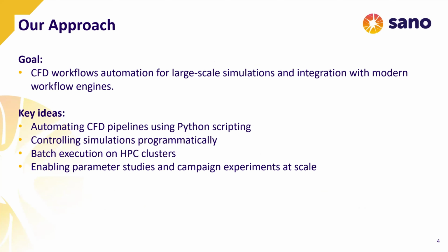From the key ideas, we wanted to take a simple CFD workflow and try to script it, then programmatically enable the simulation control and setup for the runs. Also a batch execution of multiple cases on an HPC cluster, so the matter of submission, and also to prepare for larger experiments like parameter studies.